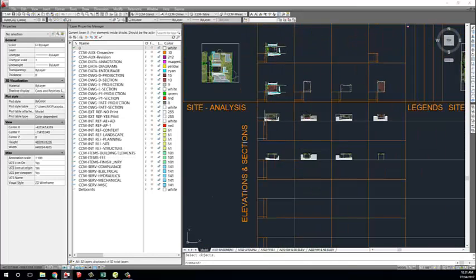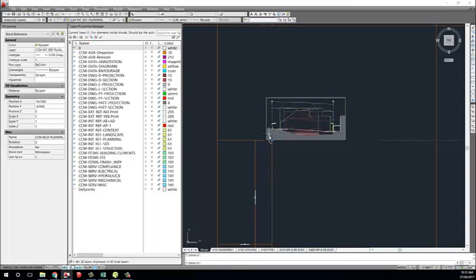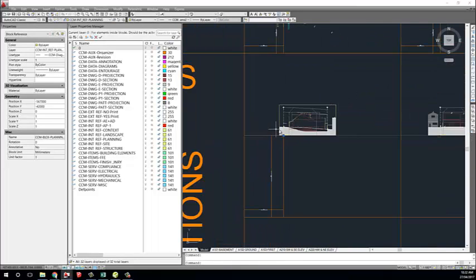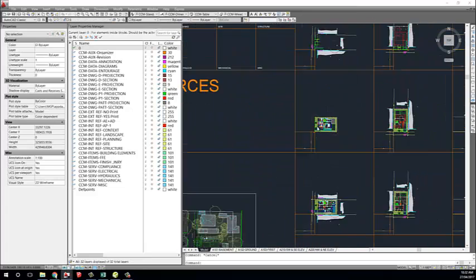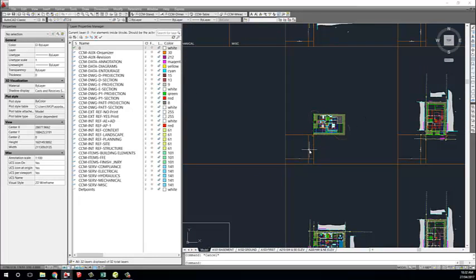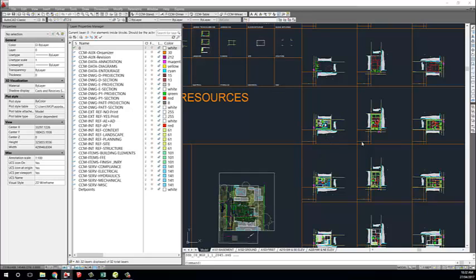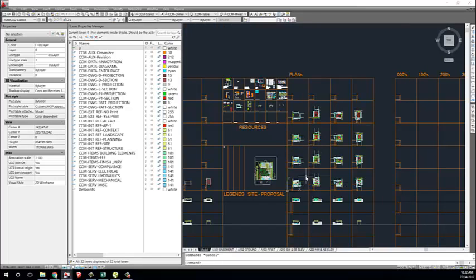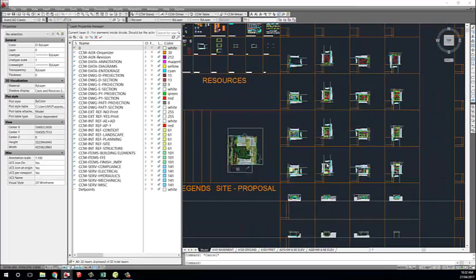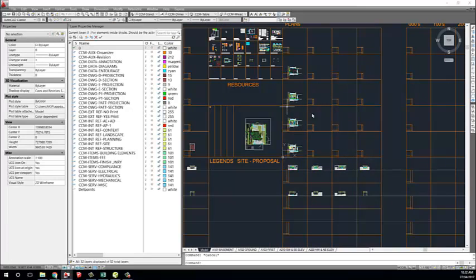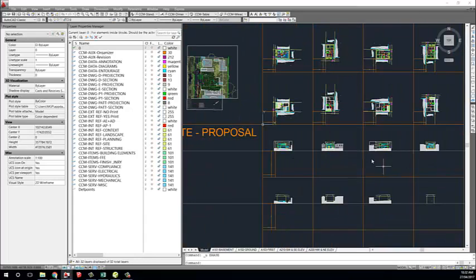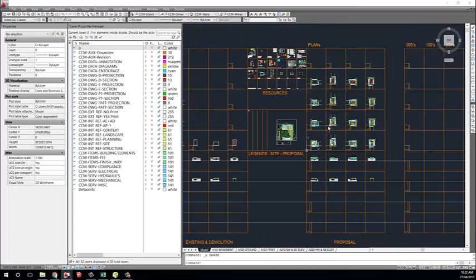These blocks have to have an insertion point all in the same place. Why? Because then it's very easy to reorganize, to delete one block, or to freeze one block and change the location, and it comes very handy. For instance, these three columns here are nothing but the architectural plans just rotated to do the elevations and the sections. So we can at any minute just delete this because we don't even need it. It isn't referenced on the layouts. But at this stage, when I'm starting to draw elevations and sections, that comes very handy.